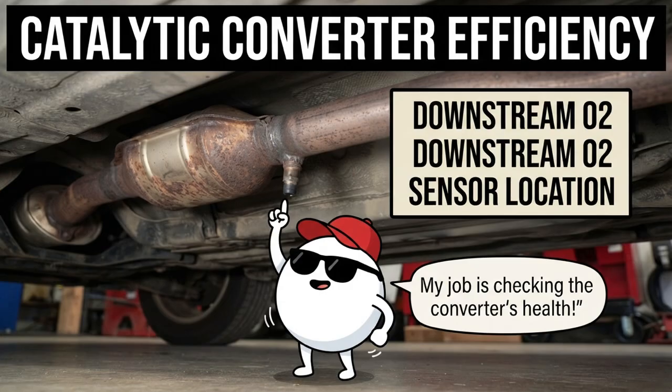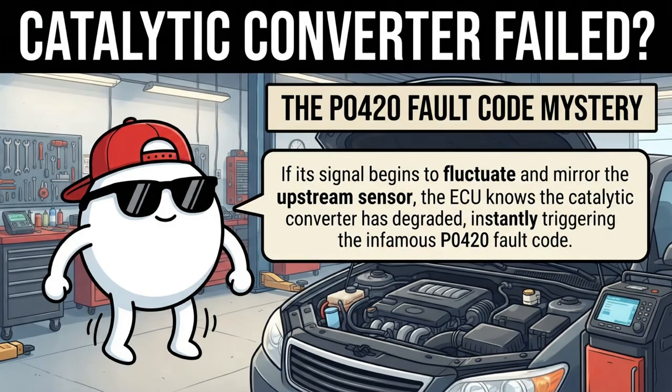The secondary downstream O2 sensor sits after the catalytic converter. Its sole duty is monitoring the chemical efficiency of the converter itself. If its signal begins to fluctuate and mirror the upstream sensor, the ECU knows the catalytic converter has degraded, instantly triggering the infamous P0420 fault code.